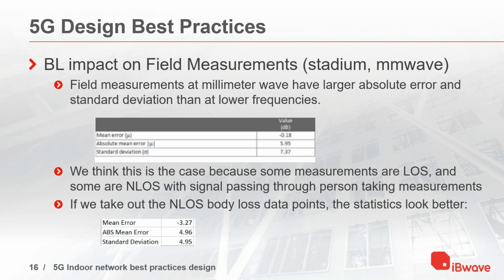Excessive as in 15 dB or more than what I had expected. I started these measurements by assuming I had only 3 dB body loss, which is the same as for lower frequencies.